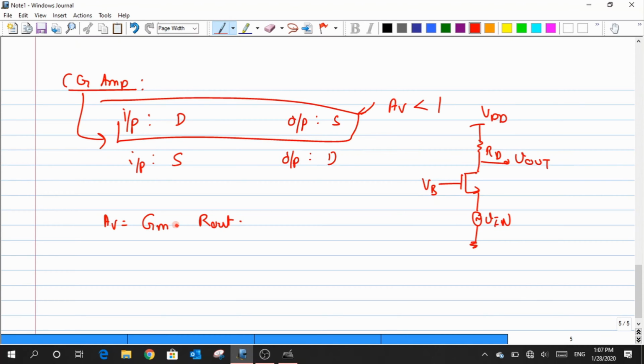So what is the capital Gm of the circuit? 1 by gm is the transconductance. Gm prime. Do you all agree with it? I'll give time, you work it out and tell me what the capital Gm of the circuit is. Otherwise you will not practice. During this capital Gm computation, what I generally do is short the output to ground and look for this Iout.